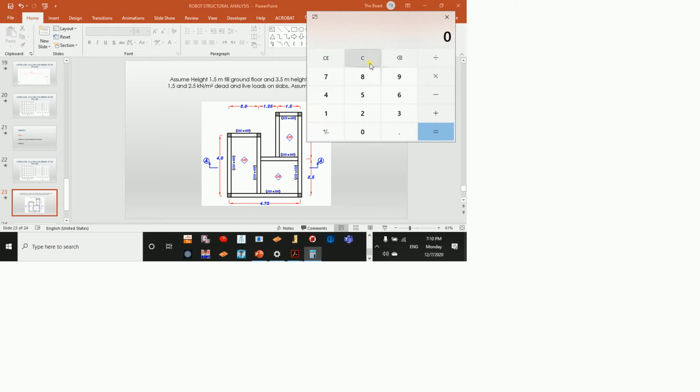The plaster unit weight is 21 kilonewton per meter cube. Normally the plaster layer is around 6 mm, but that differs. But normally in Oman we use 6 mm, 6 mm on one side, 6 mm on the other side. So we are talking about 21 multiplied by 0.006. How many sides are there? Two sides. So I just multiply it by two.